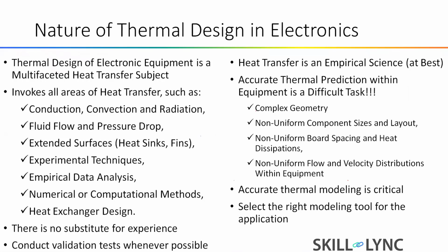Accurate thermal analysis prediction is difficult and becoming a very challenging task because of the complex geometries of the PCBs, processing chips, and even the equipment. We have non-uniform component sizes and layout, non-uniform board spacing, and heat dissipation.